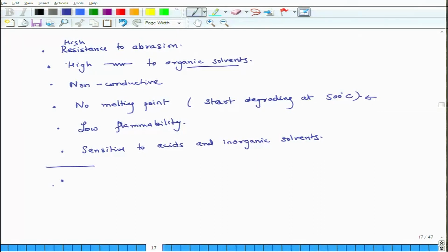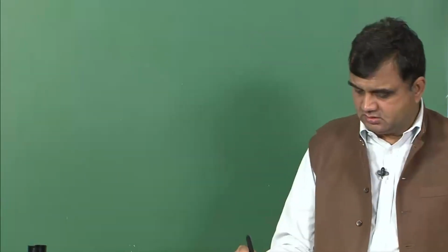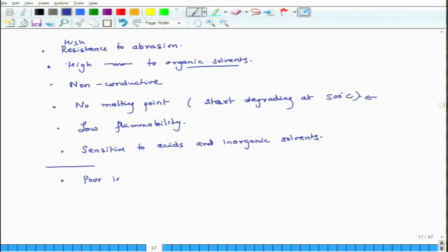If you take a Kevlar fiber and pull it, it will be pretty strong, but if you compress it, it is poor in compression. So in one direction, the outward direction, it behaves in one way, and in the inward direction it behaves in another way. So again this is an anisotropy, okay. And then the other strong point is that they are not brittle.